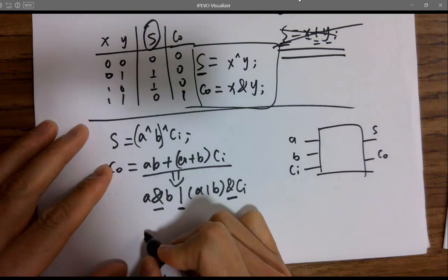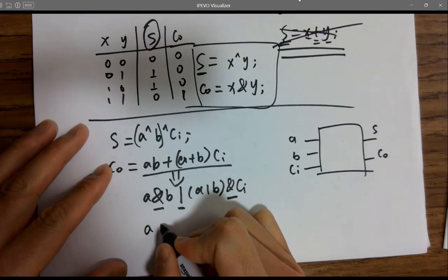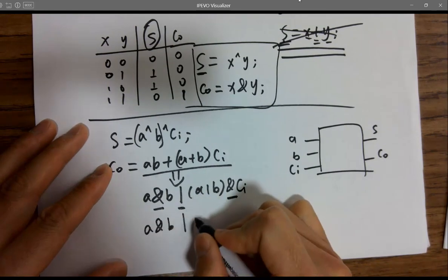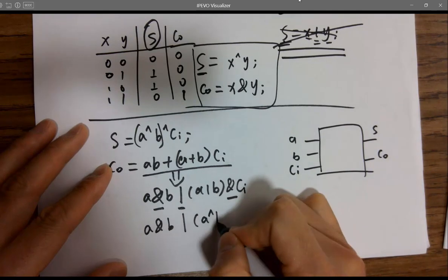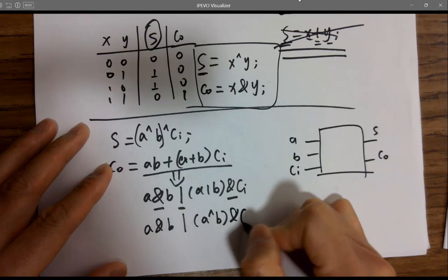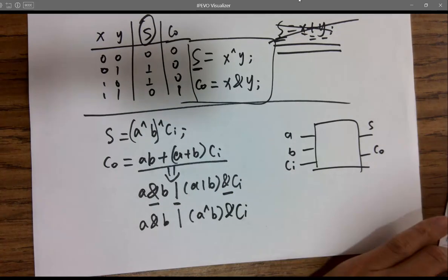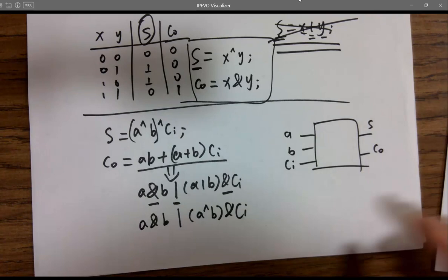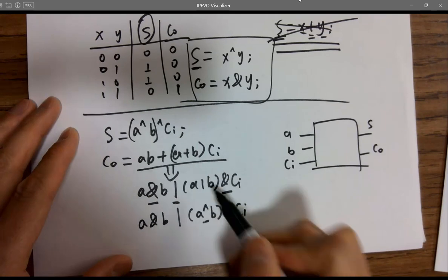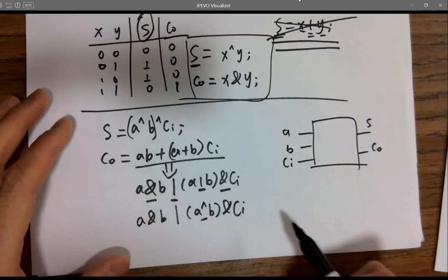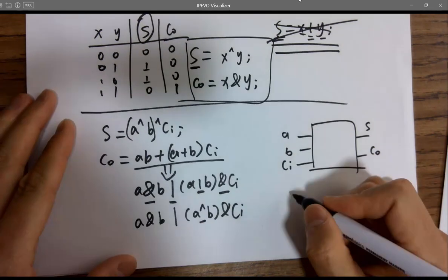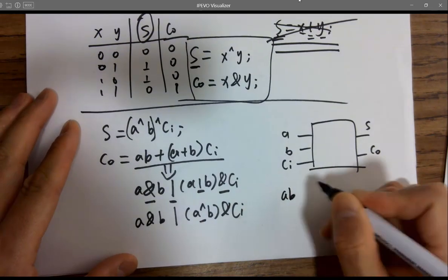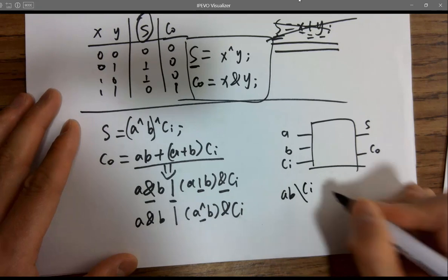You also see a format. It's like A and B or A XOR B and the CI. Let me double check. This is correct. Yeah, that's right. So you can either have XOR or OR in there. It's not going to give a different result for the full adder. It's because when you group, you have AB, CI.